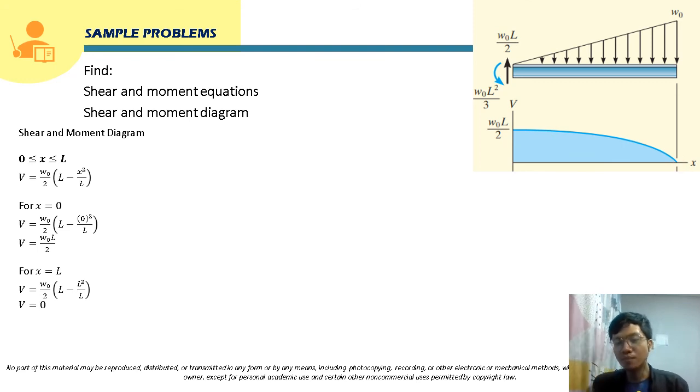So in this case, class, we are going to connect these 2 points. From the loading, as you can see here, the loading is negative increasing. If the load is negative increasing, the curve that will connect these 2 points should be concave downward, as mentioned in our discussion. And since the loading here is a triangle, of course, the shear should be parabolic.